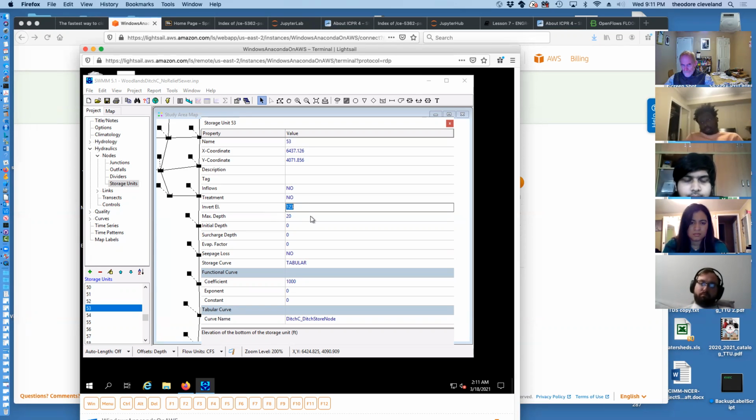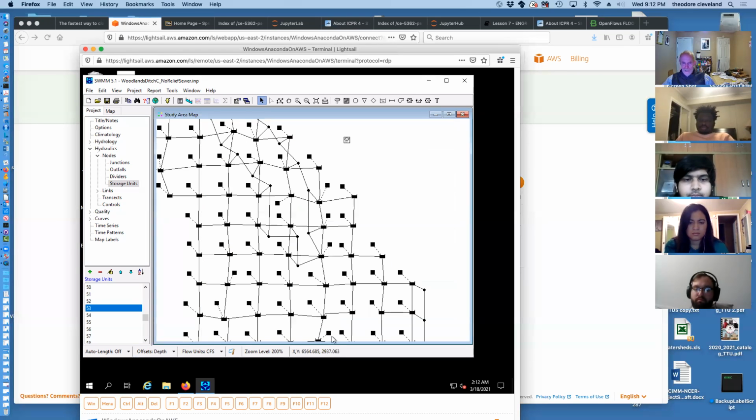So in my experience, that's the most difficult thing of using SWMM, or even the fancier models with good interfaces, of getting right, because a single elevation error in one of the storage nodes completely screws up the performance of the model, and sometimes you don't notice it immediately. And you spend a lot of time modeling and then proposing engineering changes, and then you realize you have a single elevation error. It's usually not a big deal to go back and fix everything at that point, but it's a monumentally frustrating pain in the butt, and a kill a day.